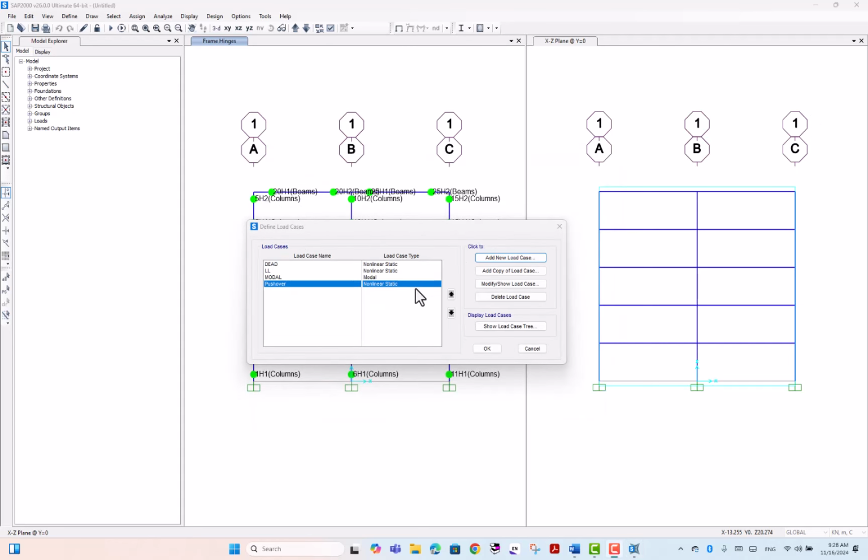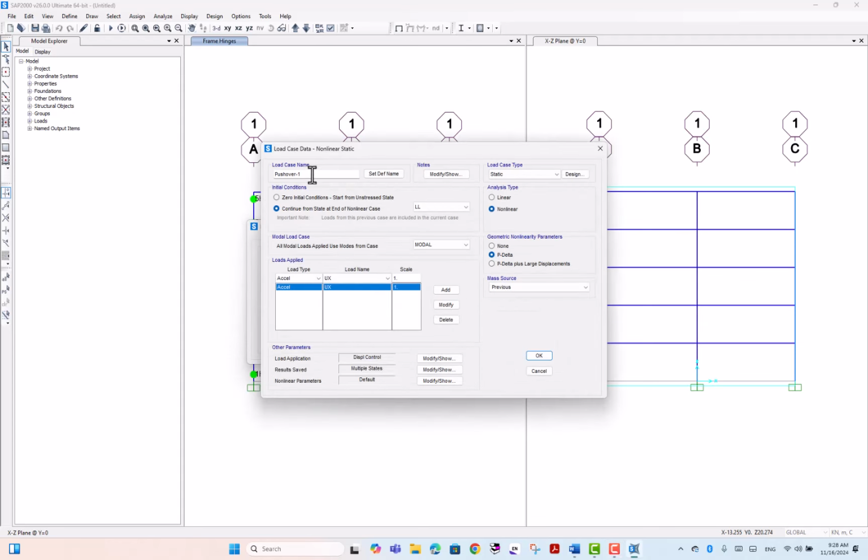Now we're going to make another nonlinear pushover analysis. We can copy this one, which is called pushover mode. But in this case, instead of using acceleration displacement control, we use mode control. We're going to take mode 1. You can give mode 2, mode 3 as you wish. So we're going to use the first mode, and the displacement control is this one, called mode steps. Same things, nothing has changed. So now okay.